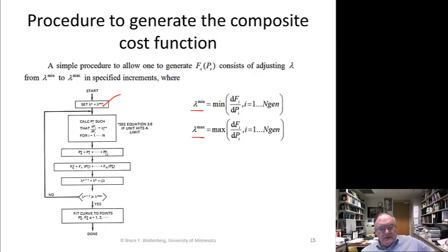And now I add the P up, and I say that's P sub S, and I've got this superscript alpha. So I say, okay, I now have the total output, and I will calculate the total cost, and then I increment lambda right here. I just increment it by delta lambda, and unless I'm up to this maximum, I go back and I do this dispatch again.